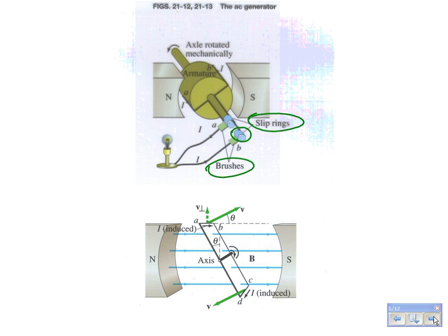There's a couple of reasons for that. Split ring commutators, if you remember with the motors we used last week, do you remember when they were turning, you could see those sparks happening the whole time? This doesn't spark because you're not making and breaking contacts all the time, and there's less wear and tear, and it generates alternating current, which has its benefits.